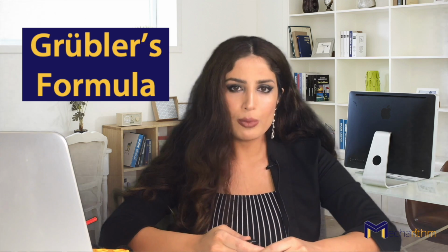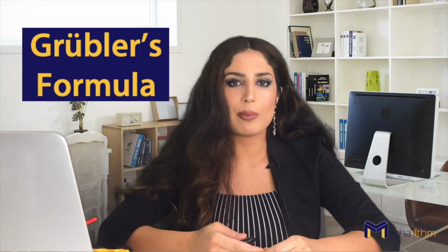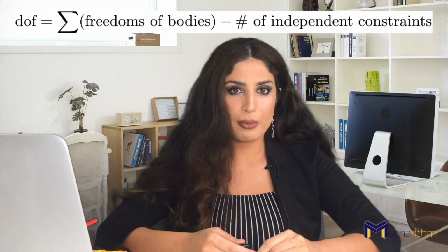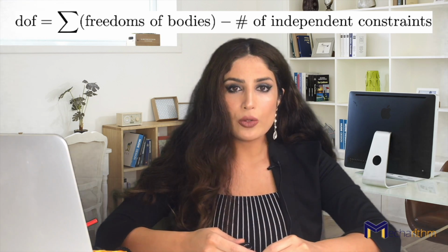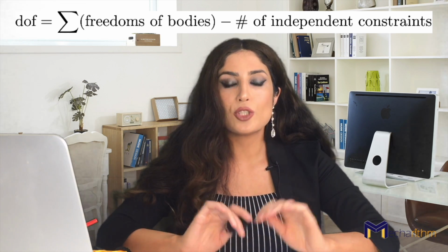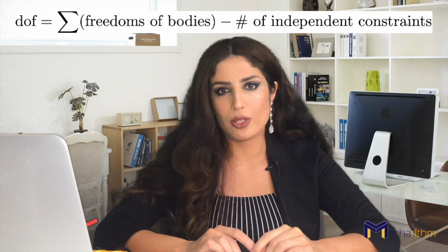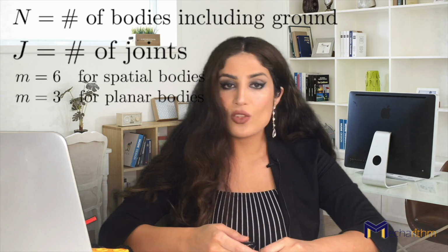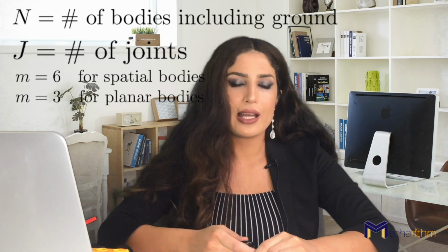Now let's talk about Grübler's formula. Grübler's formula is a general formula with which we can find the degrees of freedom of any mechanism. It's not just applicable to robots. Grübler's formula states that the degrees of freedom of a mechanism is equal to the sum of the degrees of freedom of its bodies minus the total number of the independent constraints put on the motion of those bodies. If we take n as the number of links, note that traditionally we also take the ground as one of our links.